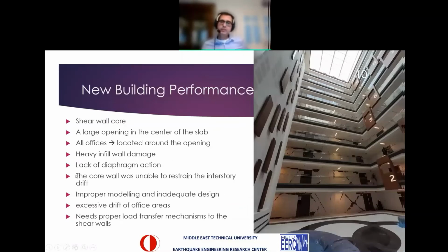Here the problem was the core wall, the shear wall, was unable to restrain the interstory drift for the rest of the structure because there's no diaphragm action over there. There's a lack of diaphragm action.